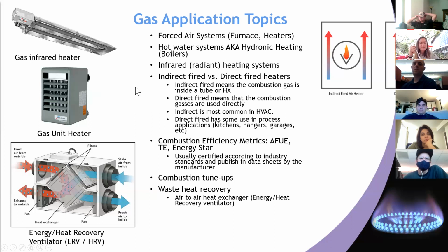A lot of times you might hear a difference between an indirect fired and a direct fired heater. So kind of the difference between these is that a direct fired heater will have the actual gas that's being burned, that combustion air, leaving with that gas, and it's part of the heat medium that's being delivered.